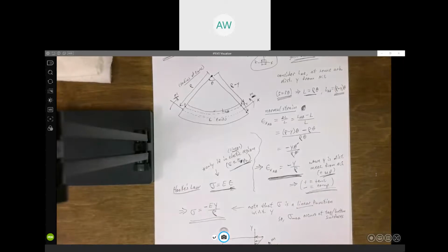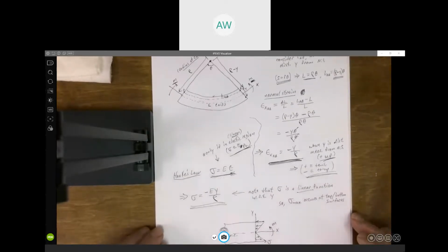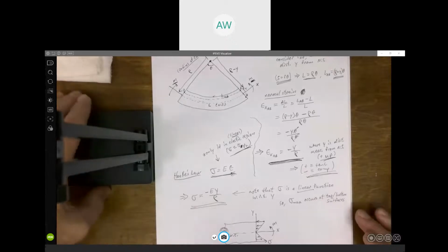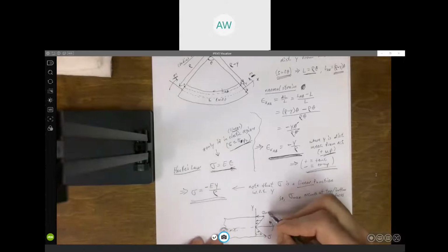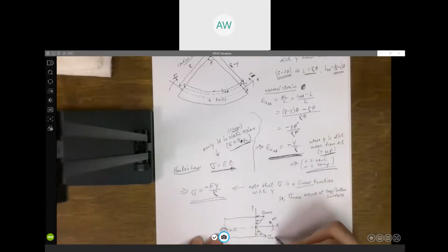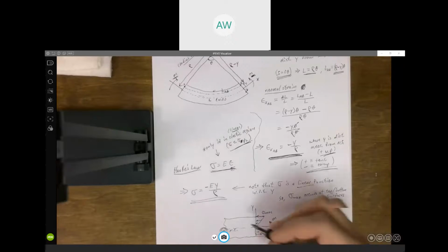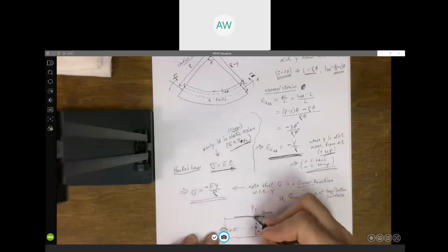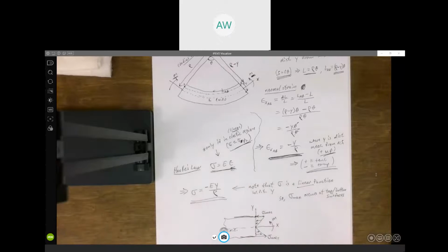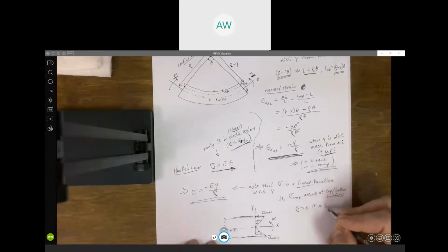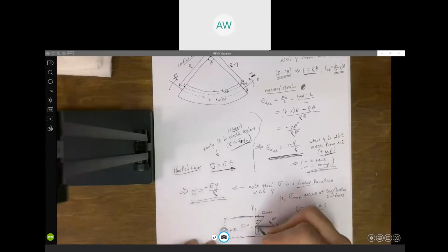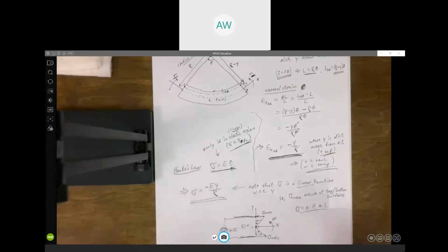So one's going to be your maximum tension. My picture is not off the page there. All right, so one's going to be the maximum. This would be the maximum compression. This would be the maximum tensile stress. But they're going to occur here on that top and bottom surface. And stress is going to be zero at the neutral surface. Sigma is 0 here. Right, so this verifies and confirms what I mentioned yesterday.